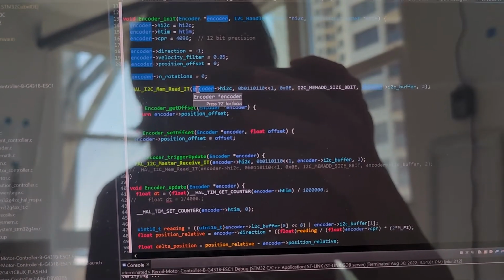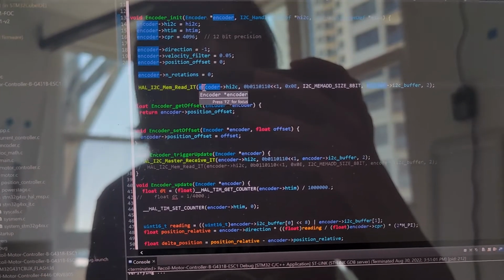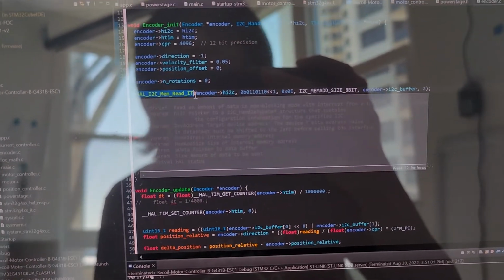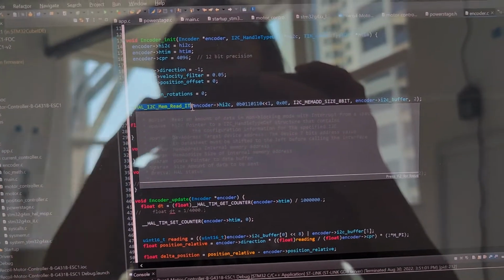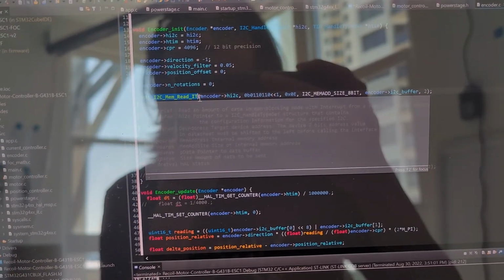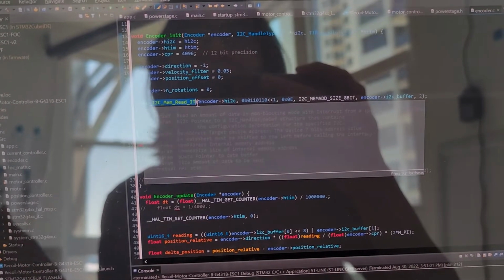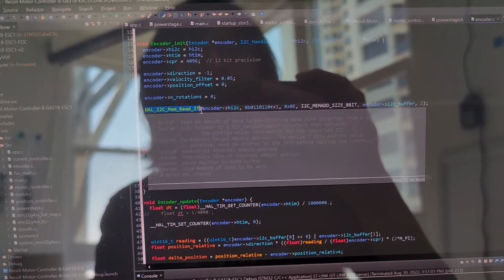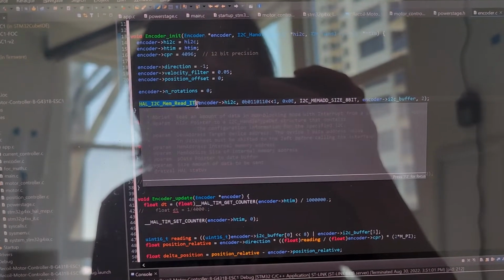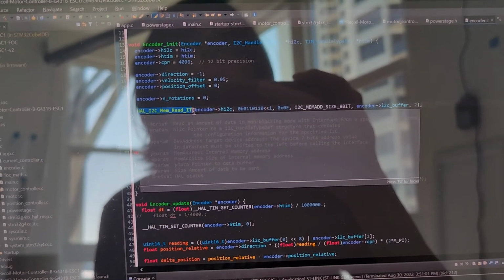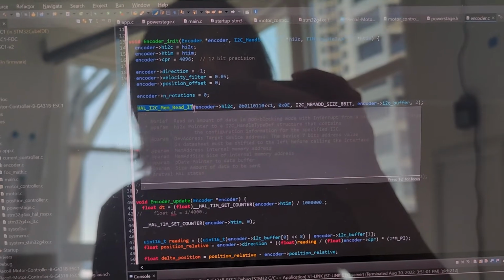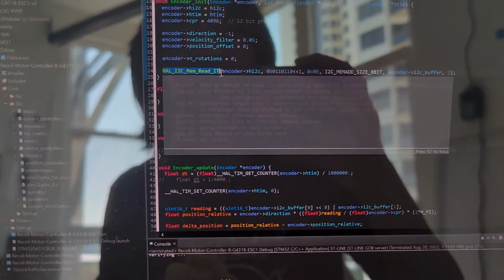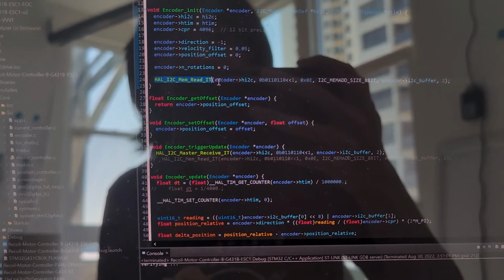It is supposed to be non-blocking, but actually I noticed that this function will get stuck for about half of the 4 kilohertz cycle, so that's like 1 kilohertz, 1 microseconds. Anyway, it's a long time spent inside this function.